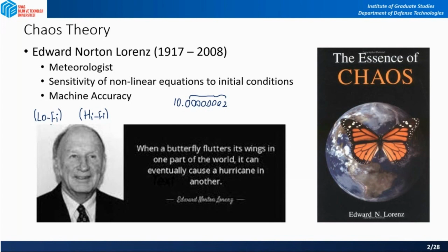So in turbulence we cannot predict instantaneous variables, but in engineering systems we don't have to predict instantaneous variables. That's the beauty of engineering. If we only can calculate somehow average variables, for example, average velocity fields, average pressure fields, average temperature fields, we can still design machines that are working with those.